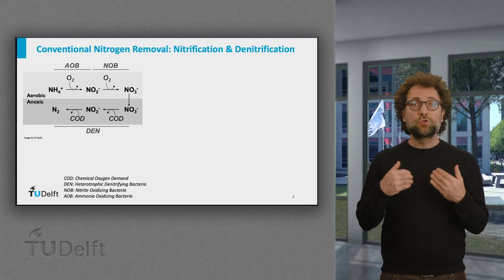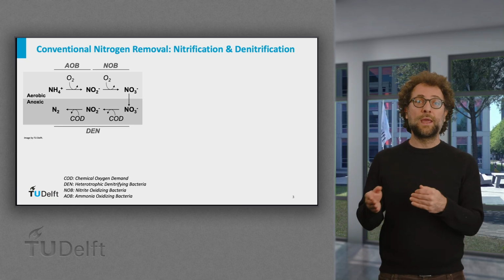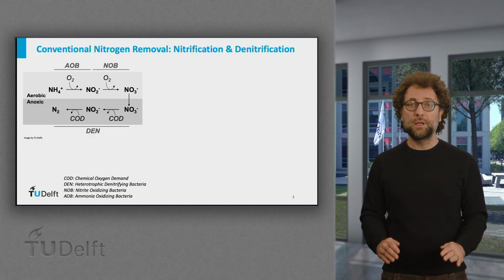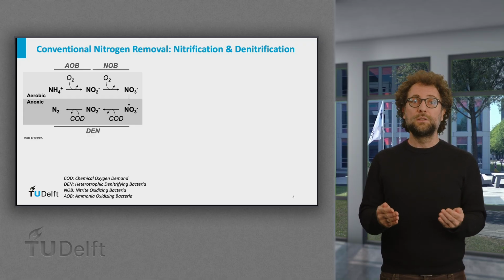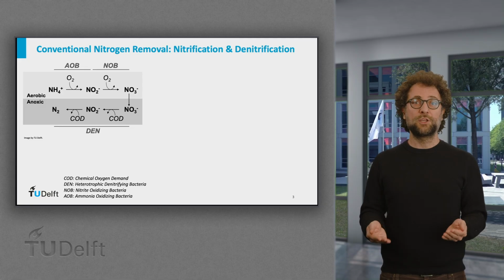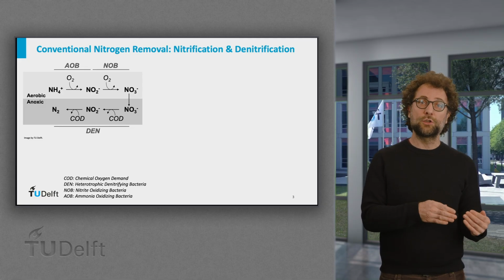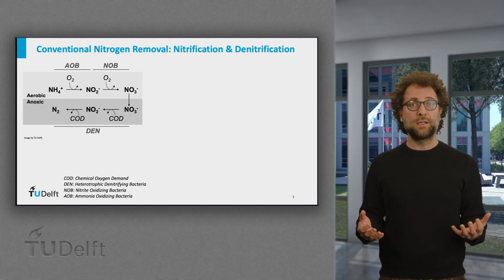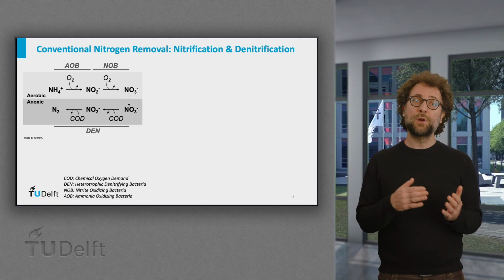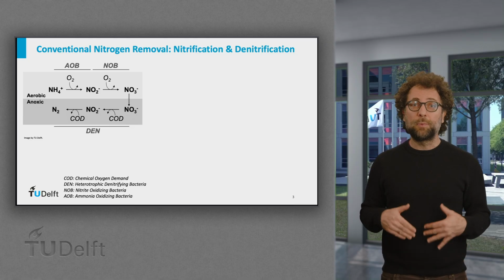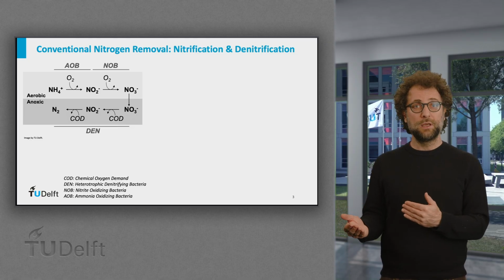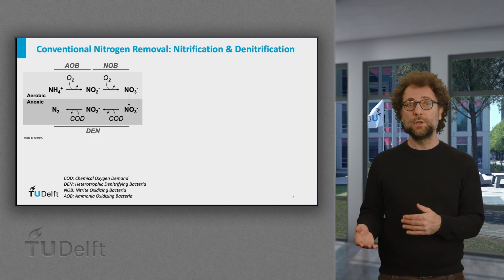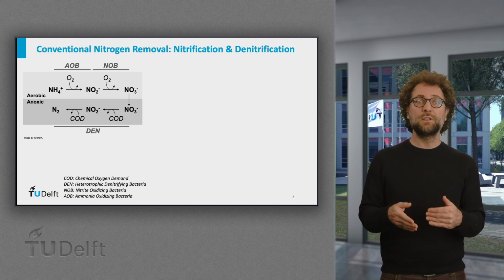The produced nitrate is then reduced to N2 via denitrification, a process requiring an electron donor, typically organic carbon, expressed in terms of chemical oxygen demand, or COD. While in most designs the organic matter already present in wastewater is partially used for this, external organic carbon addition, for example methanol, is common and represents an additional cost.